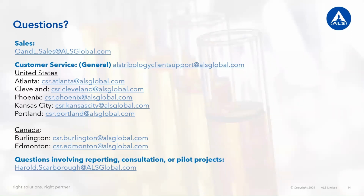I can add a little bit to that, if you like, Harold. I think what you will find is that this is happening particularly where low sulfur fuels are in use. So in the USA, we generally have less than 15 ppm sulfur in the fuel. And so sulfur acids are no longer the problem they used to be, just simply because they're not present. And so the oil's TBN is not being stressed. So now the next stress, oxidation, is a common one. So that becomes more dominant. So we're definitely seeing this in the US market.